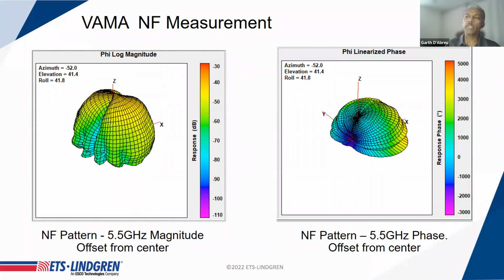If it needs a ground plane, then the vehicle body provides that ground plane. So what that means is when you do an antenna measurement system design, you have to include the entire antenna within the measurement envelope that's used for that particular antenna. And in some cases, that envelope is the full vehicle. So it means that your antenna aperture is not just the 200 millimeters of the antenna element. It's quite often several meters in diameter of the vehicle body.